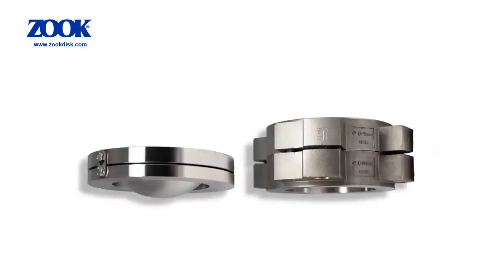It turned out that in order to reduce costs, the inlet side of the holder had been reduced to a point where the disk dome protrudes beyond the holder face, similar to the assembly shown on the left. This can create problems during installation, as it is easy for the dome to be impacted during handling and insertion into the assembly between flanges. This can go undetected until it results in a service issue, and this is what was happening. Our solution, shown on the right, was simply to provide an assembly with a similar disk style, but with a pre-torque holder that seals the disk and fully protects the dome. The problem was solved, and we have a happy customer.